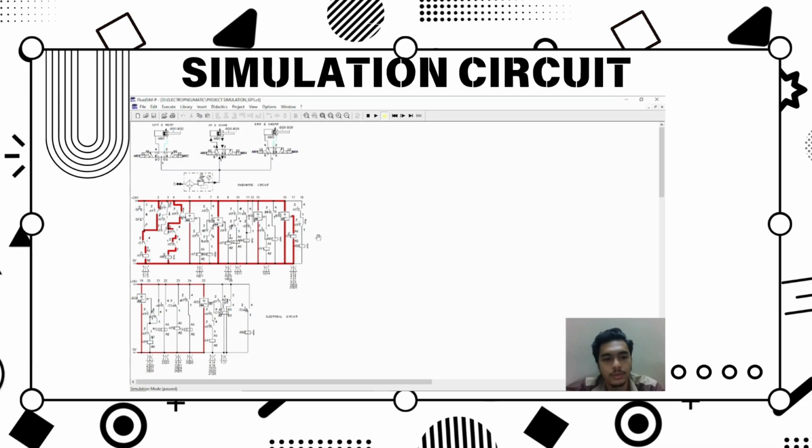Then magneto proximity sensor -BG2 will close contact and energize relay coil -KF5. And relay contact -KF5 will open and deactivate solenoid coil -MB5 here, and -MB4, which is here.